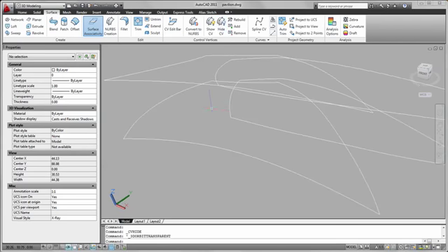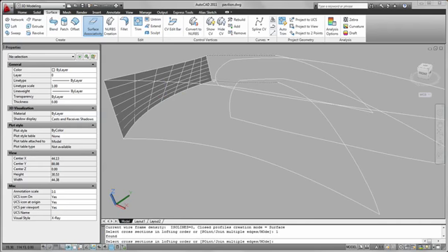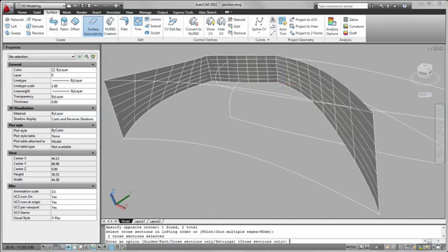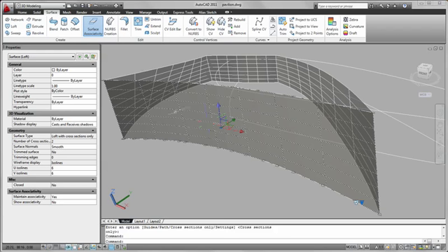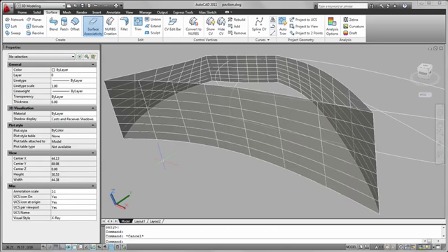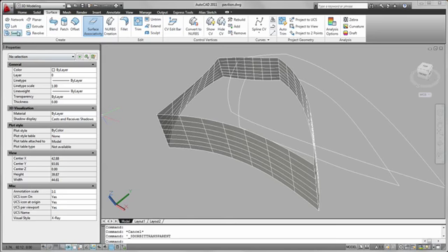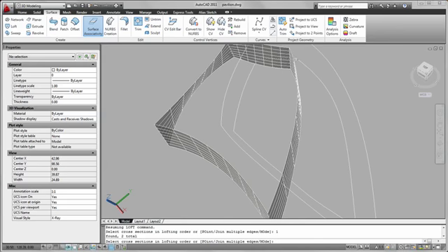In this design, the splines serve as cross-sections for my 3D model. AutoCAD 2011 offers powerful new surface modeling functionality. It enables you to create explicit surfaces with information that is relevant to a particular type of surface. For example, a lofted surface includes information about surface normals, while a swept surface includes the profile rotation. In addition to relevant surface information, explicit surfaces can maintain an association with their defining geometry. This allows for faster editing and greater efficiency when exploring iterations of the design.